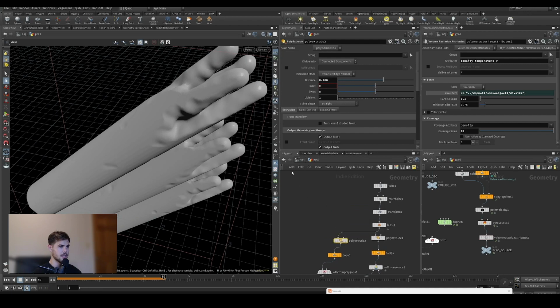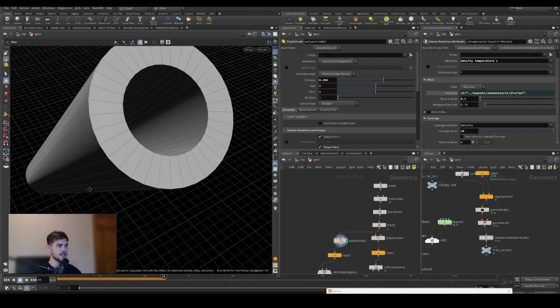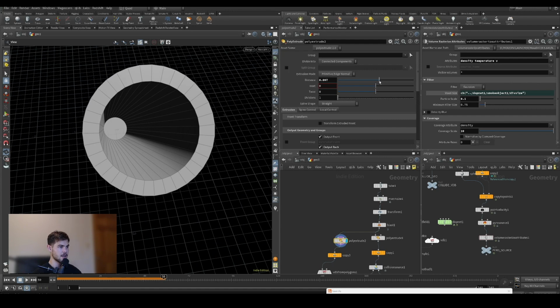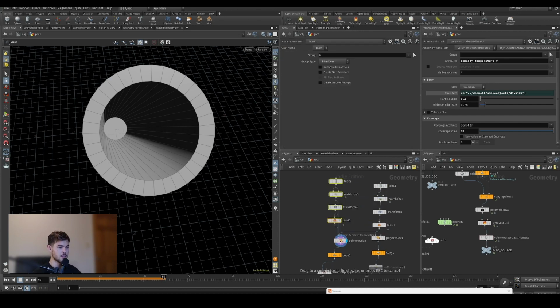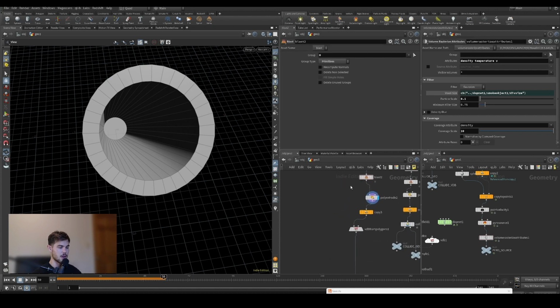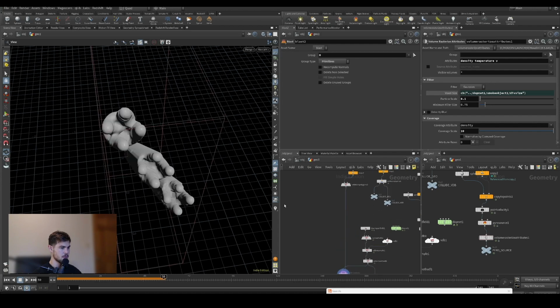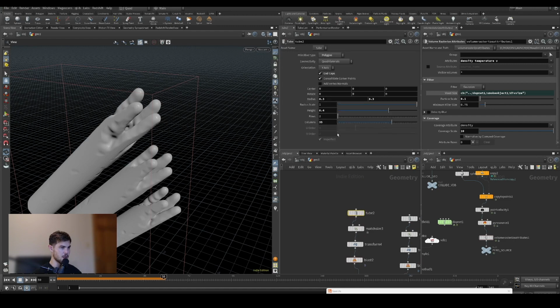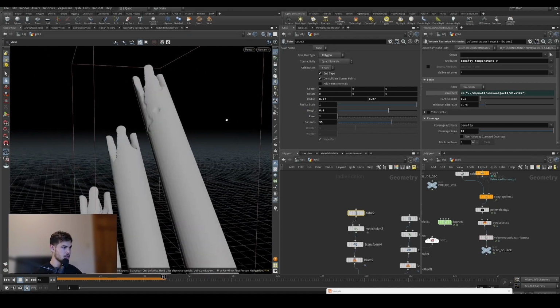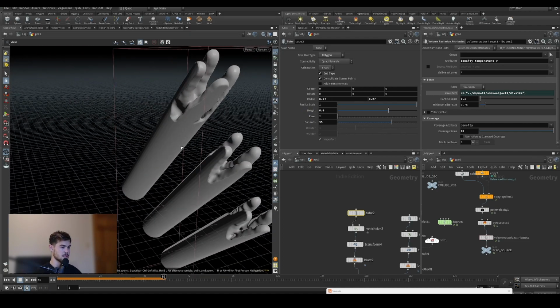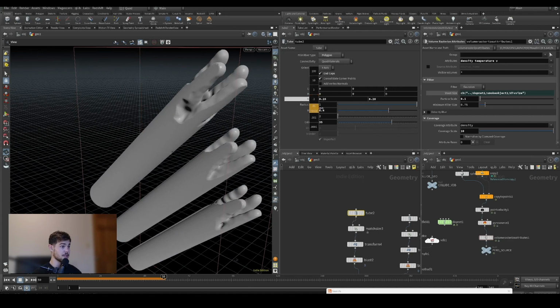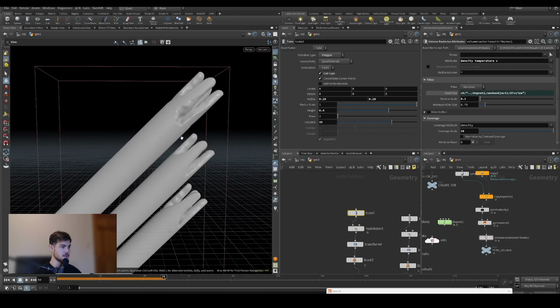And I think one thing that's happening is we might need to actually modify the inner radius of the tube. So what we can just do is create an entirely new stream for our Boolean. So here, and then we can go even all the way up to the base of our tube and dial that radius in to wherever is going to look good for what we're after. So something like that's probably fine.